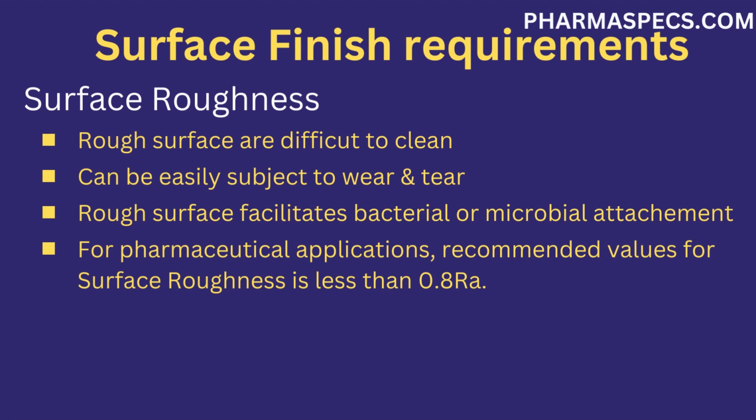A rough surface also facilitates microbial or bacterial attachment. Bacteria or microorganisms find it helpful to hide and grip to such surfaces. For pharmaceutical applications, recommended values are less than 0.8 Ra. Surface roughness greater than 0.8 Ra is not acceptable for pharmaceutical equipment application.